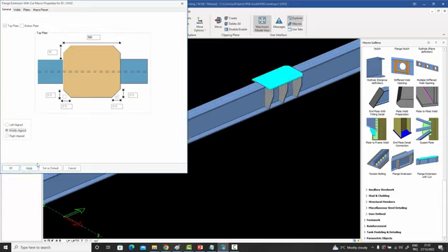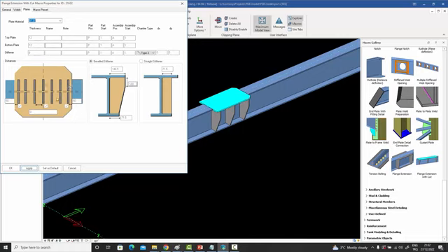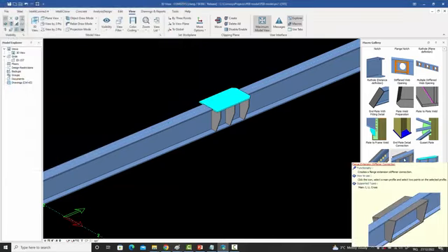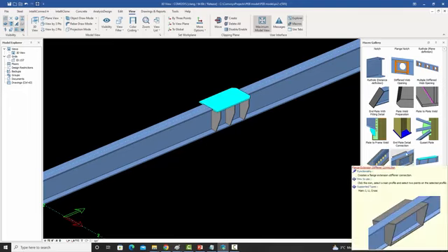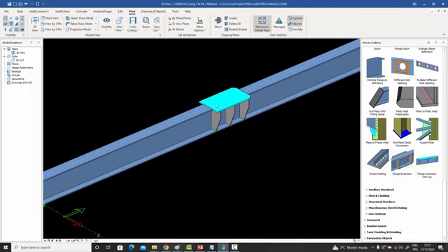And what you can do further beyond this is you can have total control over the plates, the stiffeners below. You can create as many as you want, and you can increase the width over there and all that. All these parameters are available over here. You can set your macro presets as always, and this is a very convenient way to widen the flange. We had a similar macro before as well, which is the normal flange extension, but this one actually creates two side plates. It doesn't really cut the flange, it adds two extra plates. This new one actually cuts the flange and inserts a plate at those points and gives you a widened flange.